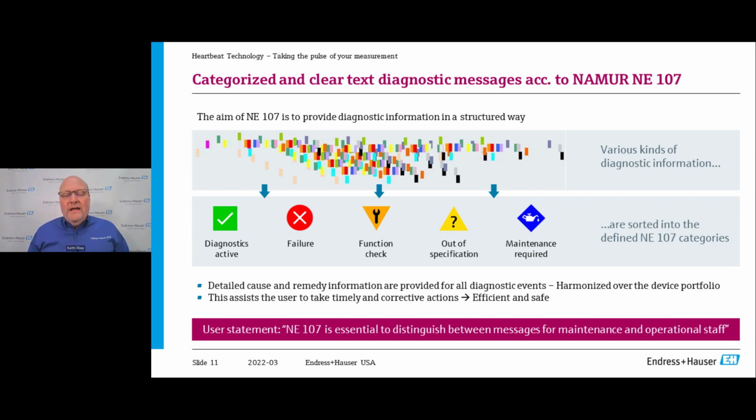When you're looking at modern diagnostics through heartbeat, not only are you getting the dashboard display you're seeing and the warning, you're also getting a plain English description on the unit of what the actual issue is. It's telling you W360 means this: I'm out of specification of the transmitter temperature, just as an example. So it tells them immediately what's going on there.